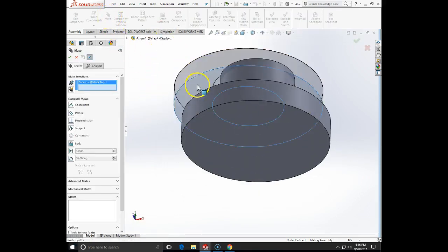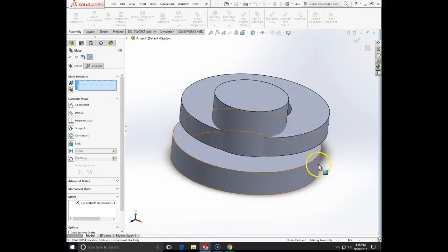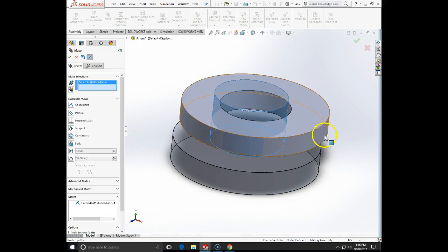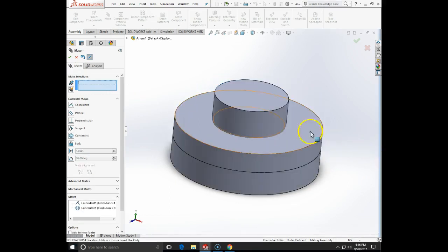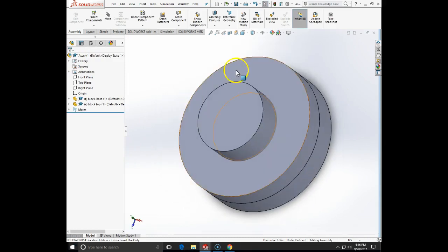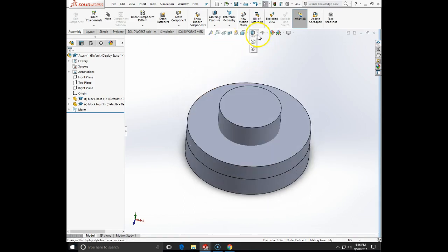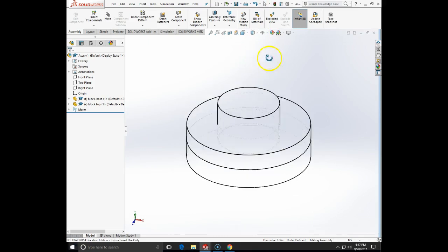I will mate this and this surface to be coincident. And I'm going to make any of the two cylindrical surfaces concentric. Now, what can you tell me if we make this object, why will it not be in assembly like this? What is the problem here that we have? Why? Because you haven't defined your...